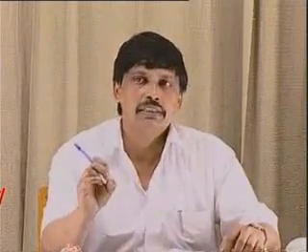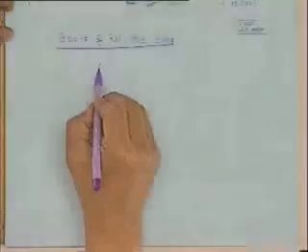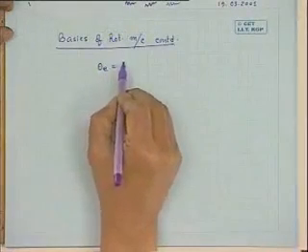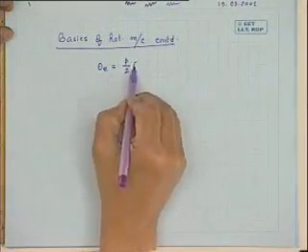Continue with the physics of the rotating machines. Last class, if you remember, we told you about some important aspects of the rotating machines. One thing is there must be a clear distinction between electrical angle and mechanical angle. And we saw last time that electrical angle is P by 2 into mechanical angle.